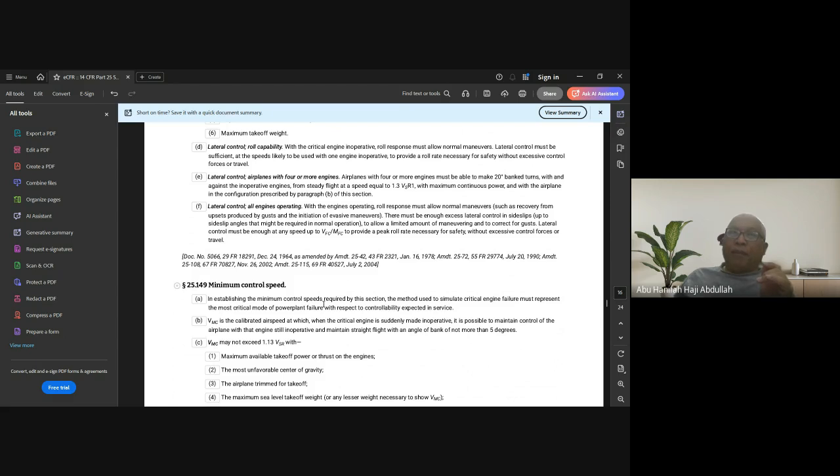If not, we've got a problem, because we are not aware it is stalling. And immediately after you stall, the best design is for the nose to start to dive. When the nose starts to dive, it starts picking up air, and then it regains lift. If you are not able to nose dive, and the nose continues up, then you'll go into a deep stall.